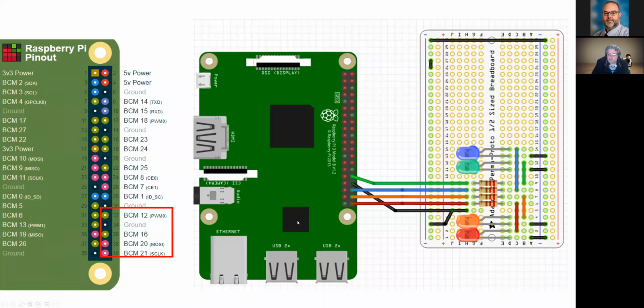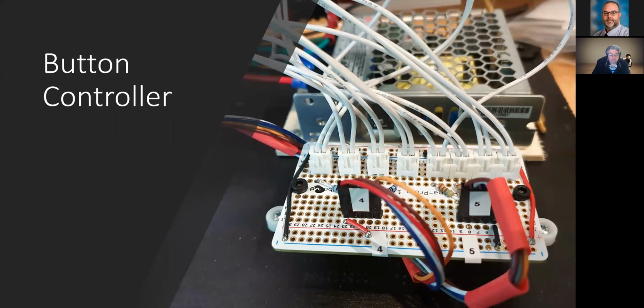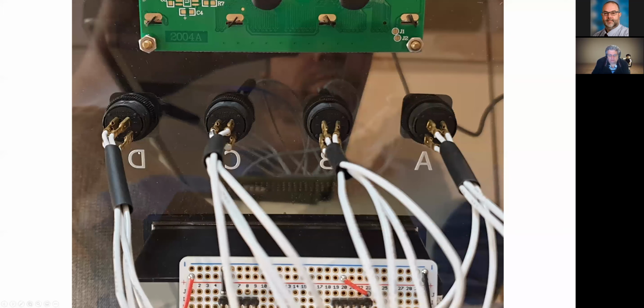So I've learned that lesson. So I'm going to connect up, say, those buttons. I design it up in Fritzing, connect those up, put in some resistors to protect the LEDs this time, and all good. And then for the buttons, because they've got the 2 functions, similar kind of thing. And then I would go off and build my little modular board. So this was the board that just handles the 4 buttons. The way it works here is on the left is the LEDs. Each of these goes to those 2 LED pins, and these 4 other buttons go off to the buttons on it, and just connect up like that.